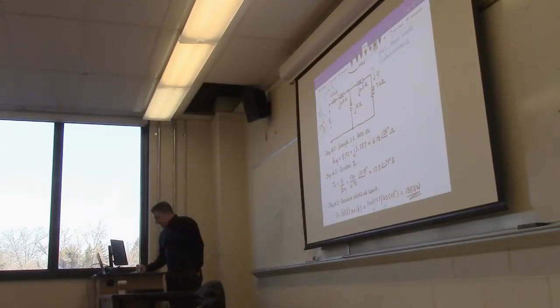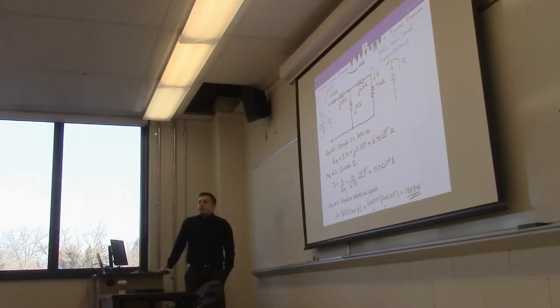By placing an element here, with the same voltage, it'll have the same voltage across it. We can design it such that the Q flows in the opposite direction, right? If one's an inductor and the other's a capacitor, or vice versa. Then, if we size them properly, we can get it such that the two Qs, the Q1 and the Q2, sum to 0.